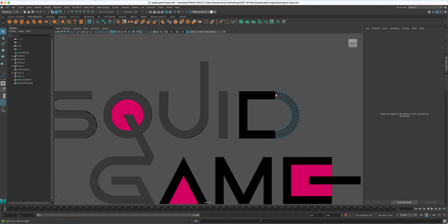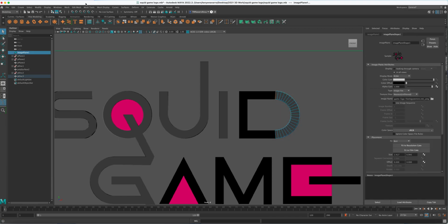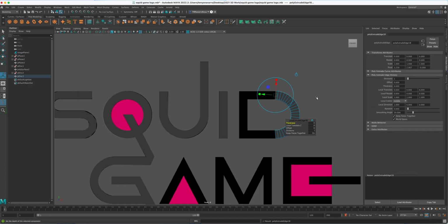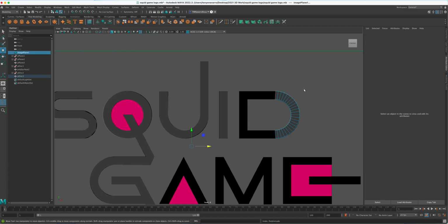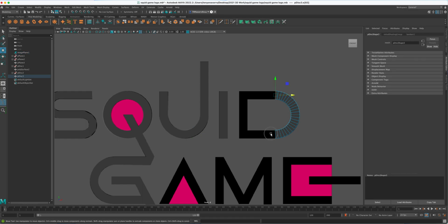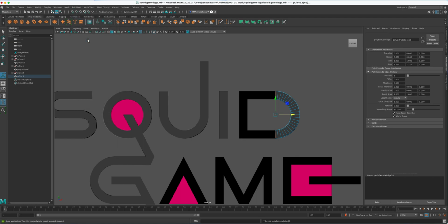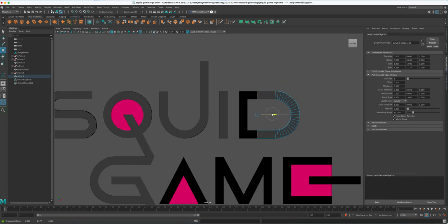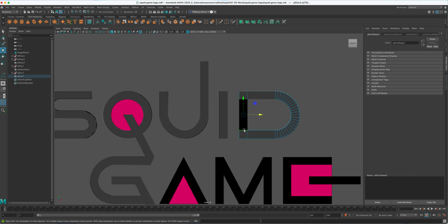Here, same thing, edge, shift click edge, edit mesh, extrude, W, in the direction where I didn't take them both, sorry. Shift, here we go, both selected, edit mesh, extrude, W, push it to here, R, straighten it out, get it close to where we need it to end, Command E, W, Command S to save what we have, click, shift click, shift right click, bridge.